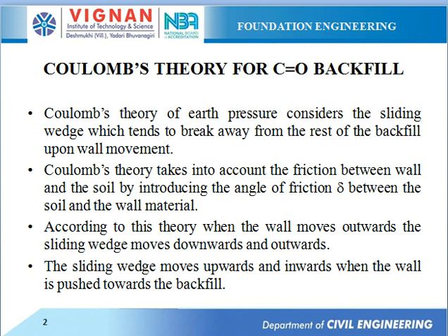Coming to Coulomb's theory for a cohesionless backfill, Coulomb gave the earth pressure theory considering the sliding wedge which tends to break away from the rest of the backfill upon wall movement. The theory takes into account the friction that will be developed between the wall and the soil by introducing an angle of friction between them.